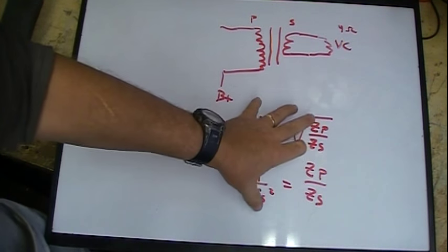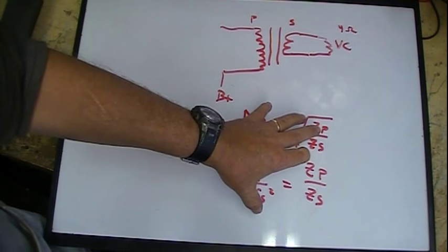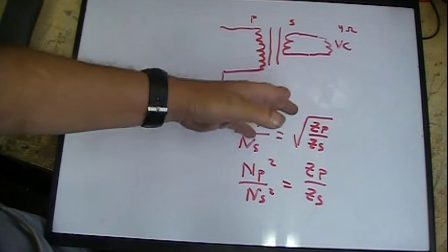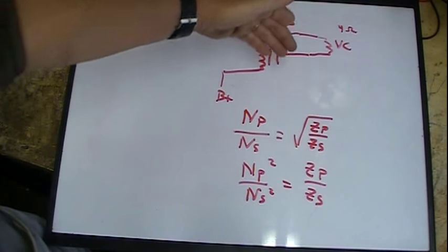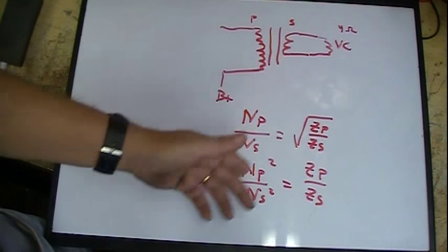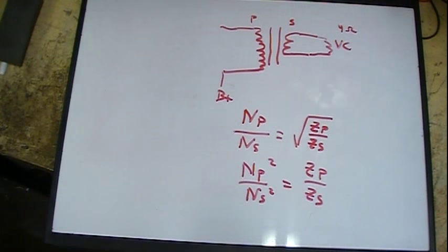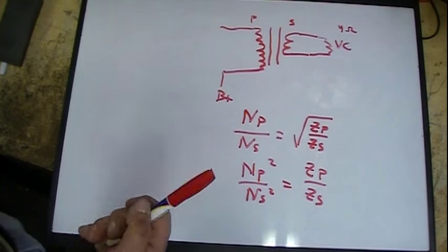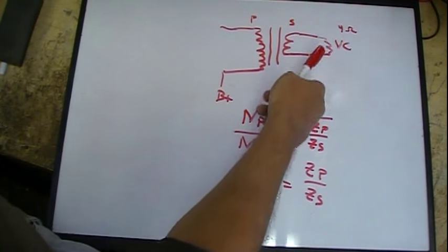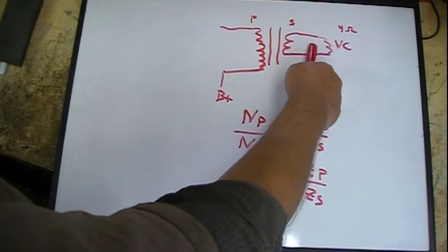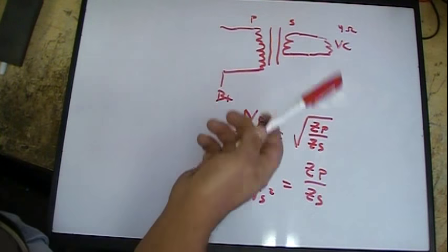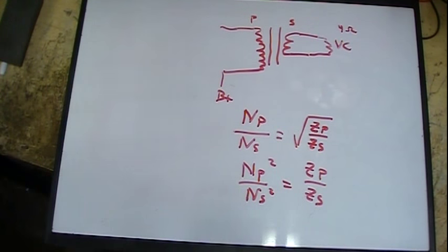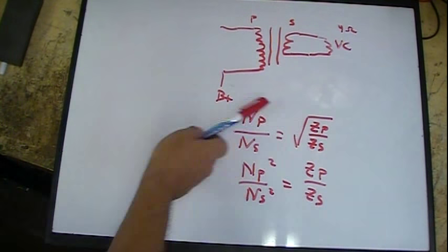And the unique thing about this, you almost don't need this unless you were winding your own transformer, because if you look up replacement transformers, they give you this information. Most places actually give you this formula. A lot of them are universal, so they'll be like 4, 8, 16, whatever ohms on the secondary, but they'll tell you if it's at 4 ohms, you'll get so many thousand ohms on the primary. But that's how it works.